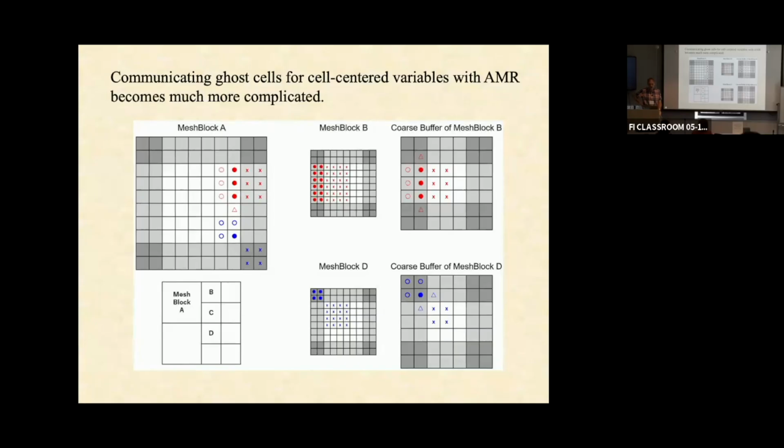With the prolongation and restriction, are you able to track those cells through time steps, or are they reorganized in the block tree? In AthenaK, at least, or in Athena++, they are destroyed and they're lost. If you create a new mesh block, then you gain a whole new block of cells that didn't exist before. If you de-refine, then that data is not stored. You throw that data away, it's gone. You conservatively average it to the coarser grid. That's the only way it lives on. The rest of the data is gone.